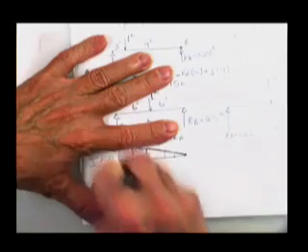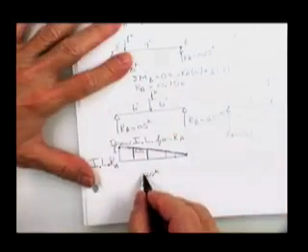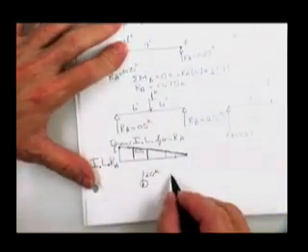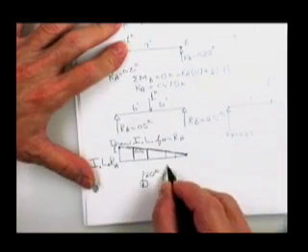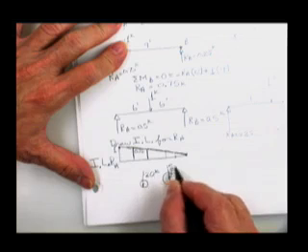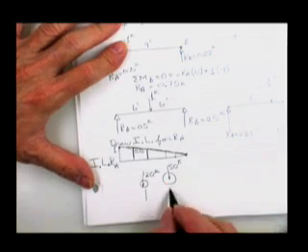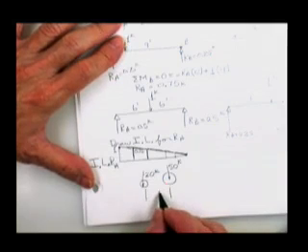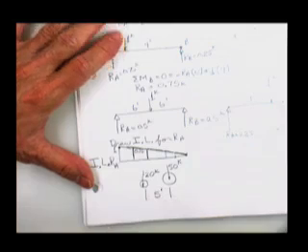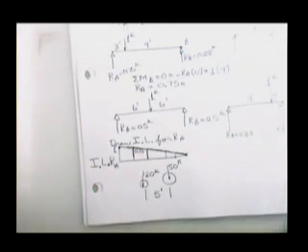If I got a truck that's got a 20 kip load in the front and a big wheel in the back which has got 50 kips on it, and they are 5 feet apart, the world's shortest truck, it tells you where to put the truck to get the biggest reaction at A. And that's something until now you probably really couldn't do.